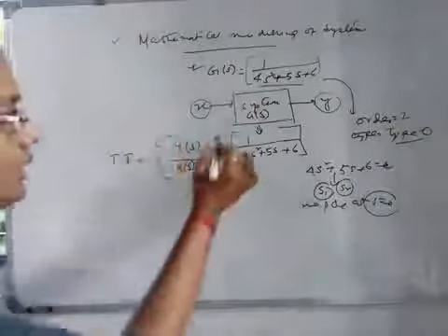In order to get the voltage across the output, that is L, or to get the transfer function, we have to write either KVL or KCL. Here you see this is your forcing function vi(t), minus the voltage drop across R, which is i times R, minus the voltage drop across L, which is L di/dt.